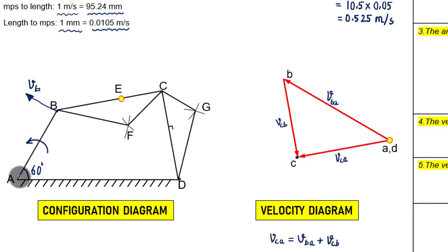So we've got all these points A, B, C and D. Now we need to work out where F is, we need to work out where G is. Now what we're trying to do is we want to find point F. With respect to link BEF or FB, keep your roller scale absolutely perpendicular with respect to link FB and bring it over to this point, small b. Just draw a line randomly, okay, very light. Then with respect to link CF, keep your roller scale absolutely perpendicular to this link CF and bring it over here to point C and then draw a line. The intersection, guys, is going to give you point F, and that's point F.